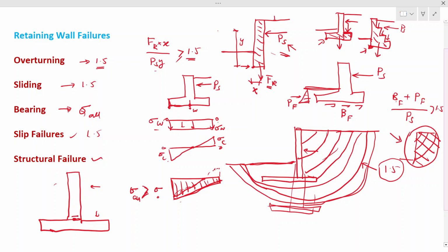So we have a very high bending moment and shear force here. So you have to design for this, and make sure there won't be failure here. You have to make sure you have provided adequate reinforcement there. In addition to that, there will be a requirement of reinforcement in the base as well, depending on the bending moment diagram. The bending moment will be maximum here, so you have to provide the reinforcement. You also have to make sure the deflection requirements are met as a serviceability requirement. And for the base as well, you have to do the same thing: the reinforcement design, and make sure the reinforcement is provided adequately.